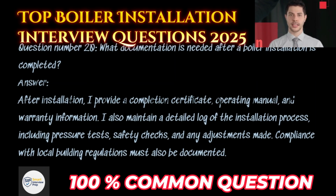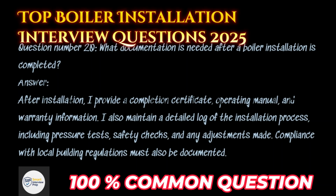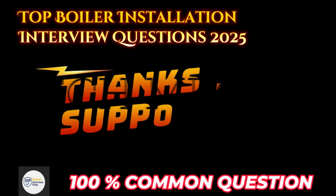Question number 20. What documentation is needed after a boiler installation is completed? Answer. After installation, I provide a completion certificate, operating manual, and warranty information. I also maintain a detailed log of the installation process, including pressure tests, safety checks, and any adjustments made. Compliance with local building regulations must also be documented.